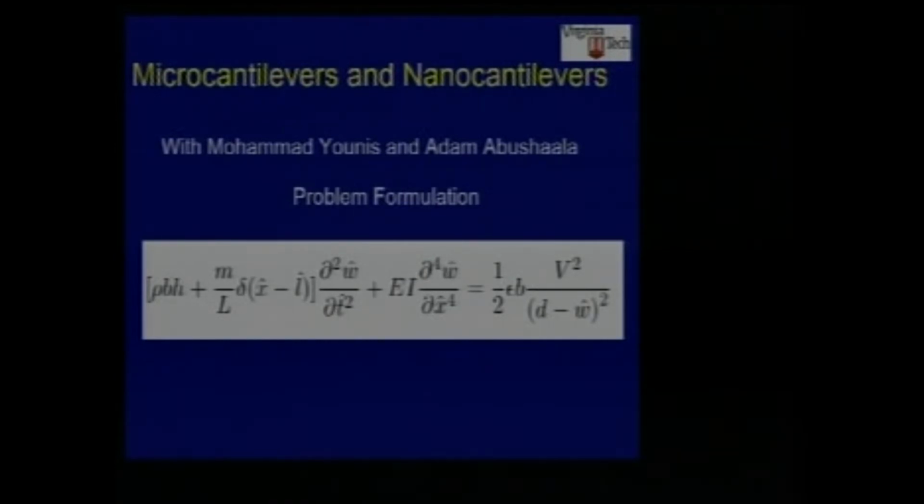So that we have a cantilever. It could be a beam, it could be a nanowire, it could be a nanotube, although here it's talking about the nano beam, nanowire, or the micro beam, because if it's the nanotube, we need to modify this electric one. So that you have essentially a beam equation, and since it's a cantilever, the nonlinearity, whether it is elastic or inertia, is small compared with this, so that the nonlinearity which you have is coming in from the voltage.